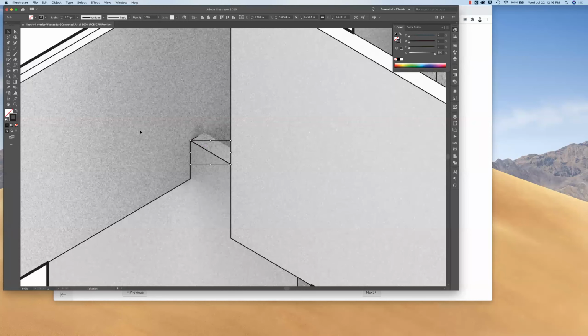Right, so I can take this line, I can actually use this cursor and just select one of the endpoints of the line and just make sure it snaps precisely. I can just find this point and move it to there. I can draw a new line and go from here all the way to there, right? Just a couple places it seems like it really has problems. That's not quite parallel. I'm really anal about this.